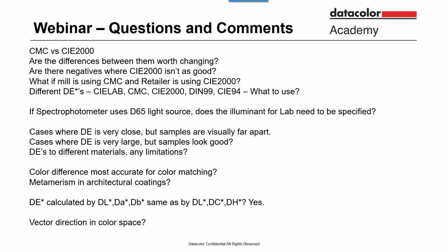Even if you go out and you buy a paint in a store and you come home and you paint half your house, and you run out of paint, when you go back to the store, probably what you want to do is get the same paint from the same store so you get the same formula. However, if you went back and just matched the color, the store would match it again, there's a possibility that they would come up with a different formula based on possibly a different spectral arrangement, and you could be in trouble. So metamerism occurs all the time, and it's really based on when you're doing color matching or creating a new formula from scratch.